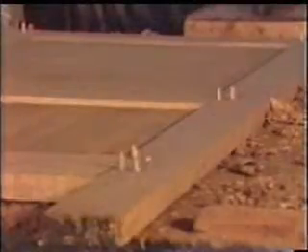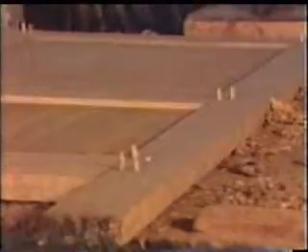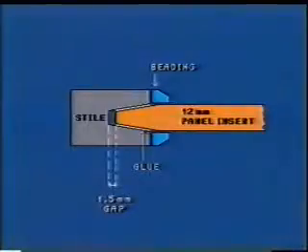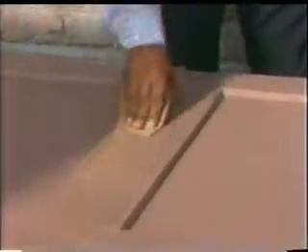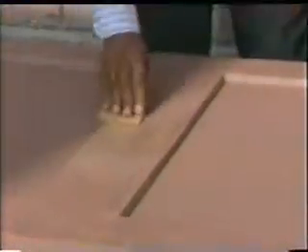Check that all joints have 2 bamboo pins each in a staggered position. Open a sample door to check that edges of panels fit in the groove, leaving an air gap of 1.5 millimeter for expansion. Beading should be provided at the junctions. Scrape the priming coat at certain locations for checking its evenness. The species of wood should also be checked at this stage.